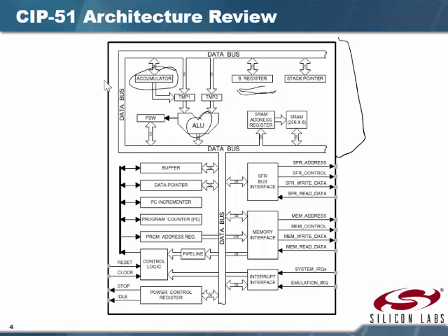And then over here we have something called the stack pointer. Now the stack pointer points to the stack. Now the stack is a location in memory that's used for what I would call post-it note type data. Things that we want to keep there, but not for long term. The most common use for the stack is putting addresses on an interrupt. Whenever an interrupt is called, the microprocessor has to know where to go back to.